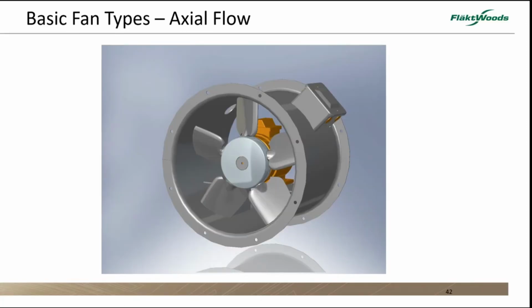Right, the axial flow fan, in principle, a very simple product. And a round duct is something that sounds very easy to say, but it's not always easy to make. When you try and roll a piece of steel, even with flanges on it, it has a tendency to want to try and turn itself into an egg shape almost. So the skill is in the manufacture, because the rounder you can make that duct, the better.